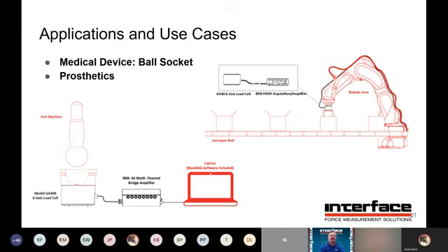And so, say you're measuring the wear characteristics of a socket, you'd really want to understand what the forces are, and then be able to duplicate those in some kind of a long-term test so that you can study, say, the differences between different materials and whatnot. But obviously, if your test conditions aren't the same between different types of specimens, and you don't know what was causing earlier wear out on one versus the other, if you don't know for sure the loading conditions were the same.